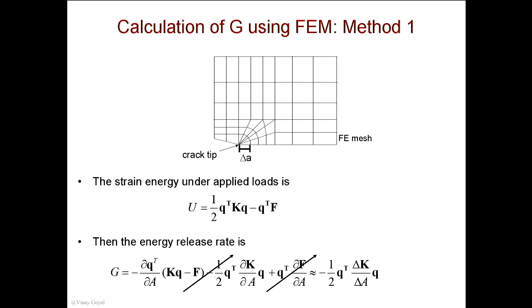The strain energy on the applied loads, we've already covered this. The strain energy is basically the deflections of the whole system, transpose, times the whole stiffness matrix of your finite element, times Q, minus Q transpose F. Now, Abaqus actually gives you this value for the whole model. It can plot that for you. In fact, for your buckling model, I encourage you to plot the strain energy. You can actually plot that.